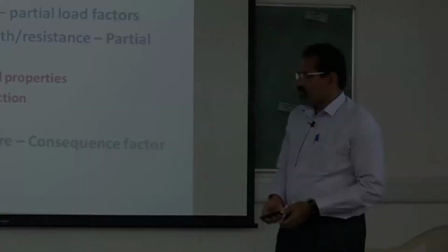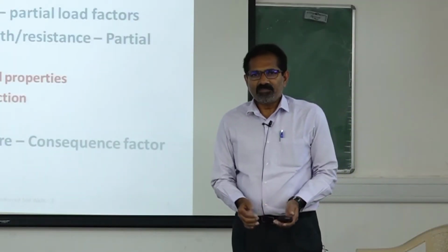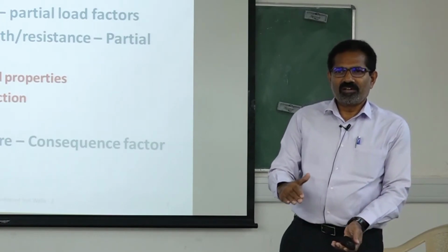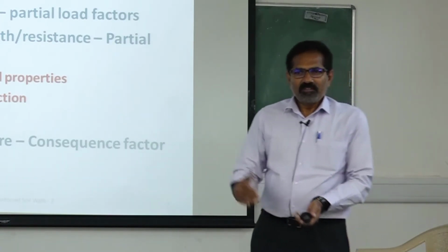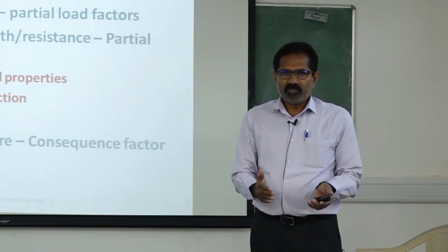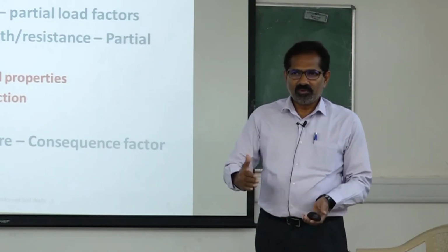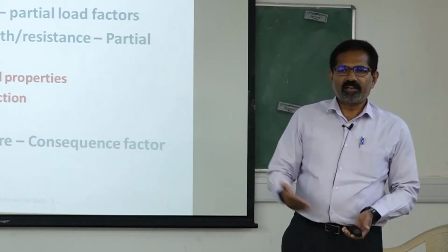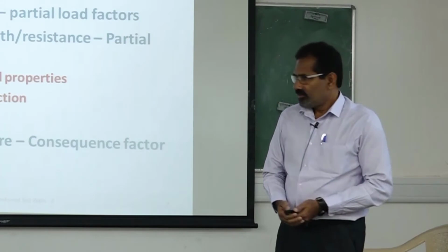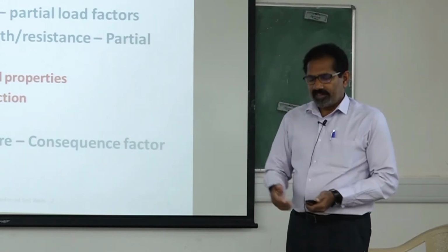Another is consequence of failure. If it is a small unimportant structure, for example a small retaining wall for landscaping, even if it fails, there is not much of a problem. But if it is a highway retaining wall, which retains a road or an airport or a railway track, failure means large consequences. So probably we should use a larger factor there.